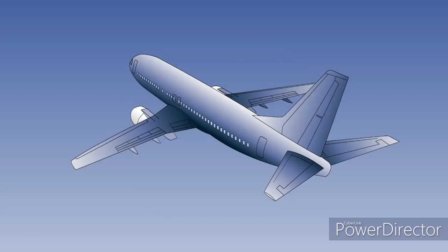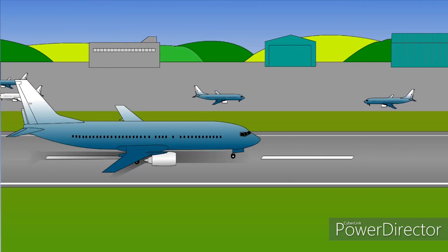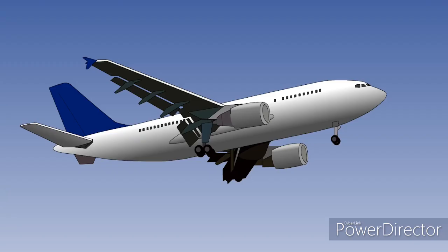A safety factor is built into these speeds to allow for aircraft age and the response time of an average pilot. Because there are distinct variations in an aircraft's handling characteristics in certain configurations and stages of flight, minimum control speed, VMC, has three separate specifications, which are VMCA, the minimum control speed in the air, VMCG, the minimum control speed on the ground, and VMCL, the minimum control speed in the landing configuration.